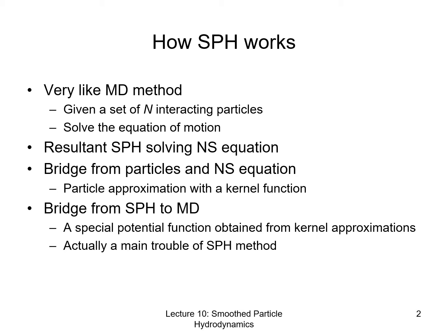That means sometimes they may have trouble with so-called macroscopic artifacts, because the SPH method is solving a macroscopic problem, but sometimes its behavior is like a microscopic approach. But this microscopic behavior is not physical, because physically the SPH method needs to solve macroscopic physics and should only represent macroscopic behavior.